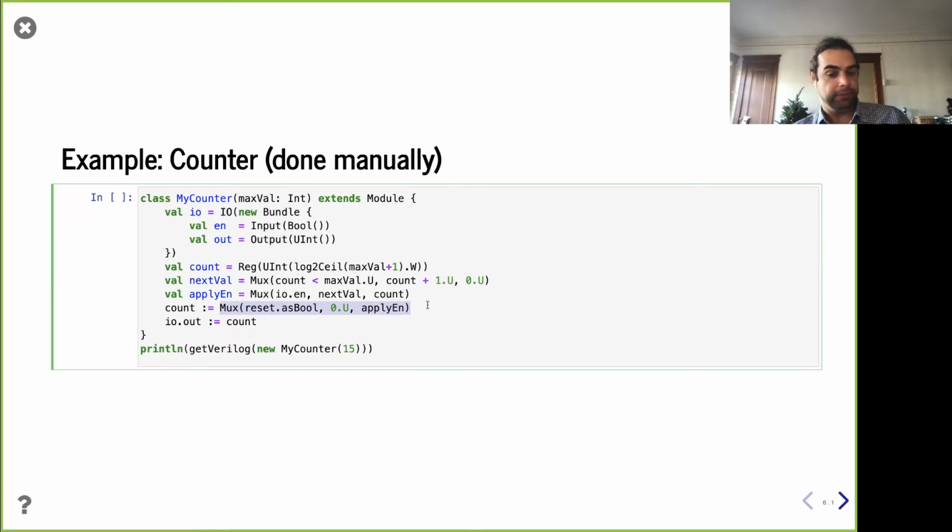So if you're counting at home, you're saying, wait a second, I ended up with 1, 2, 3 muxes. I use the vanilla register. If I use one of those spiffier registers, could I perhaps reduce the number of muxes? Definitely. But the reason why I wrote it this way is in a few slides, you're going to see me kind of change the code, and it'll make the code transformations more clear if it's always kind of vanilla register and then working with muxes. But here's kind of functionality, right?